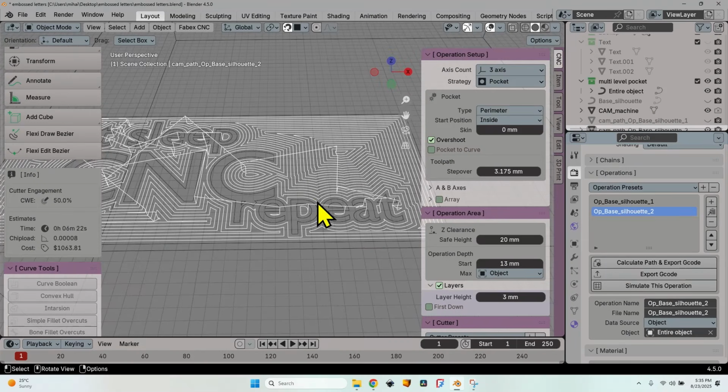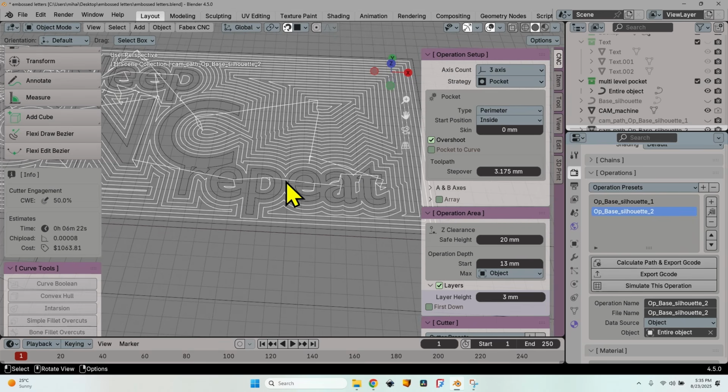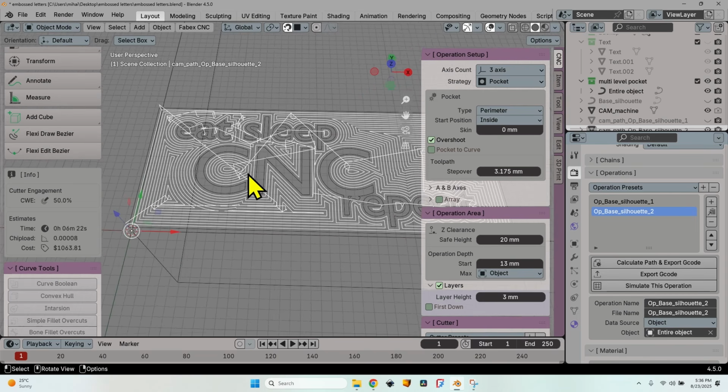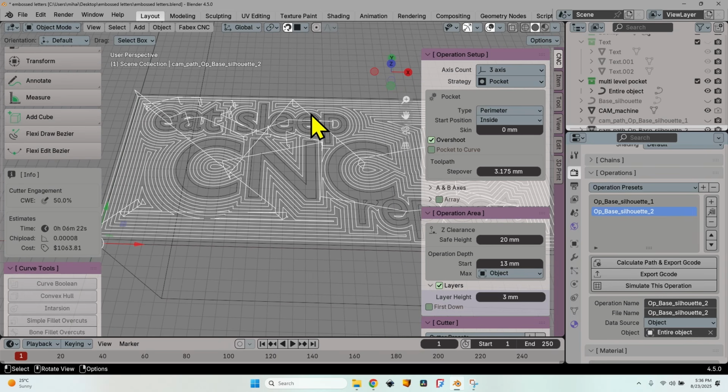So as you have seen, and it's easy to see in the 3D view, there are some portions that haven't been cut because the cutter simply doesn't fit in these areas. Let's solve this. Let's make a new operation with another tool bit. I will change the tool bit, reset the Z value, and then we will make a new operation. But I don't need to mill all this material because it is already milled. I just need to follow the contour.